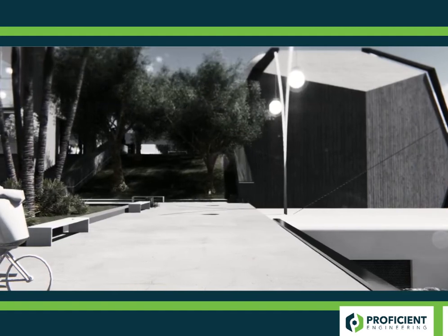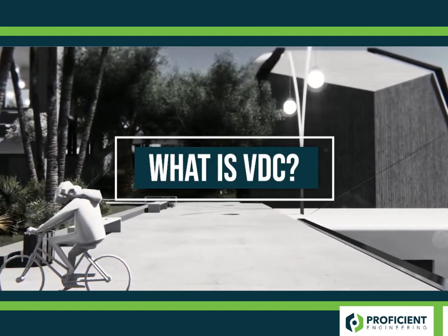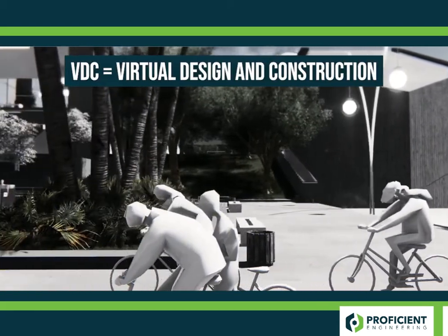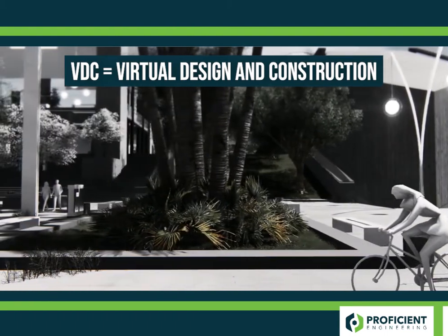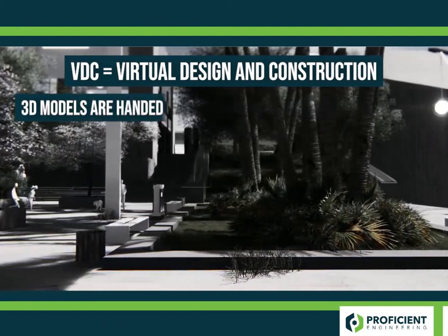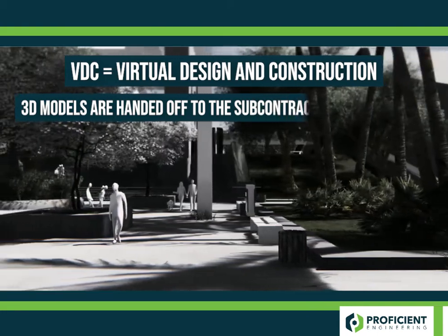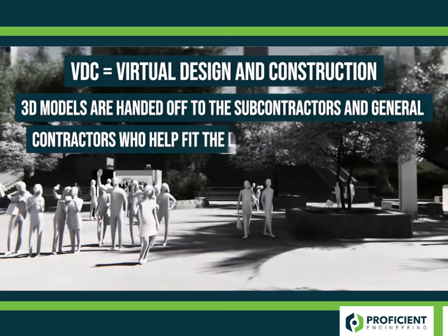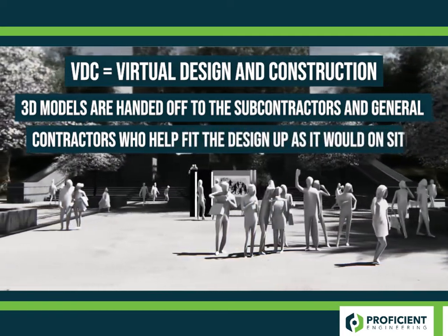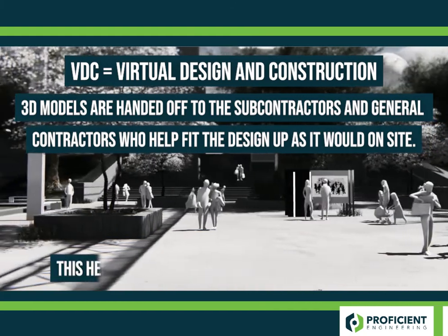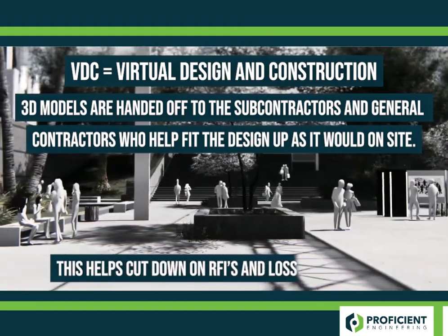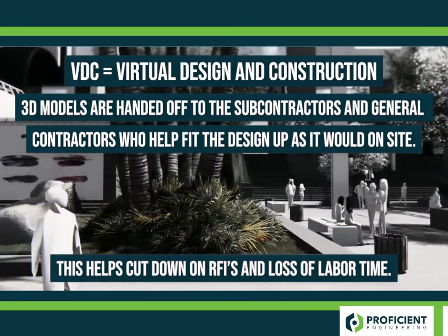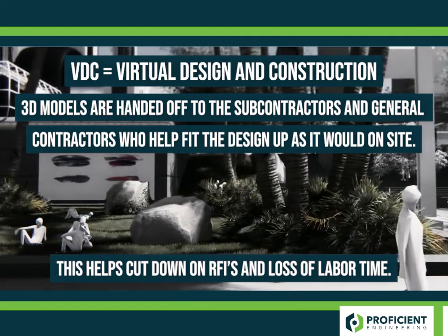And a big term that's used is the VDC. Can you explain what that is? Yeah, VDC is virtual design and construction. It's where the design team creates 3D models, either with Revit or some other BIM software, and hands it off to the subcontractors and GC. The subcontractors and GC then pick it up, and we fit it up as they would on site. This helps cut down on RFIs and loss of labor time when fitting up a building, because we do it remotely and get all the coordination work done.